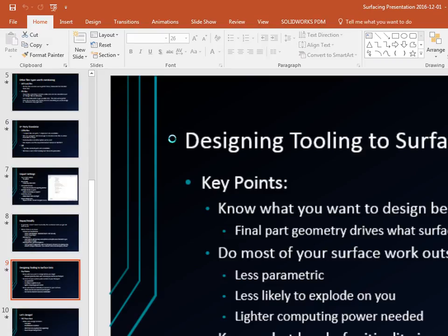So even filleting these edges is an option. It's a design decision that I made. I could have squared off these faces and actually made a mill cut on this edge. We do that quite often, we'll just mill out a flat area there, a recess. Exactly. If I don't care about that corner geometry, I'll just clear it out with a squared off end mill. That would be a separate cut feature. But this one has enough angle to it that it's going to be kind of junky in this area.